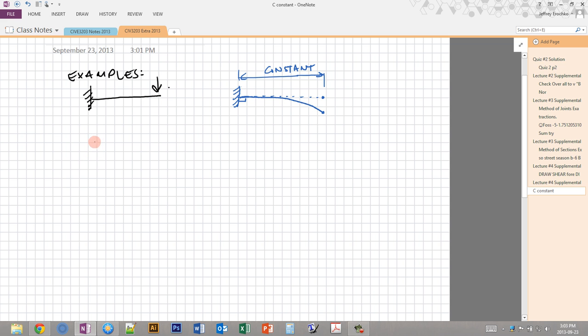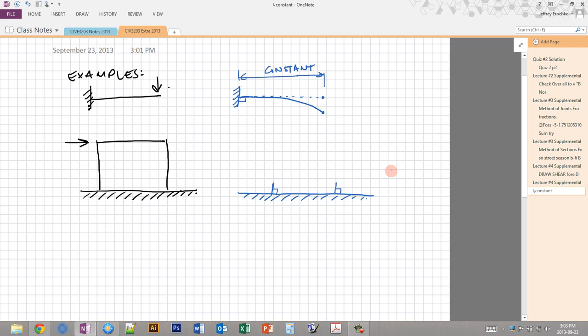Say we have what we call a portal frame, which is just 2 columns and a beam that connects them, all rigidly connected, and we put a force over here. Okay, well, we can draw right away. We know that the fixed ends are going to remain fixed. So let's draw this. We have a fixed end here, and a fixed end here, and these remain 90.